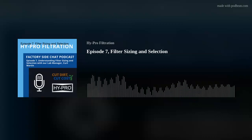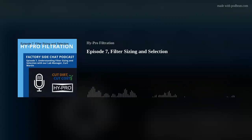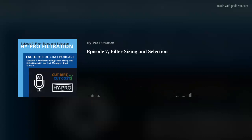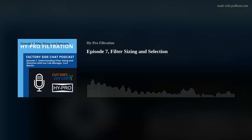What we see with that is it's easy to do because dimensionally they're the same size. And the reason, no fault of their own, is that somebody looks at the price difference and it's a big difference, and they say, well, it's the same size, it fits, I can save some money, maybe a third the price of a high collapse filter element, and then here we are. So I assume that's one thing that you definitely want to vet out if there's an existing housing and they want to confirm the filter element in that housing.